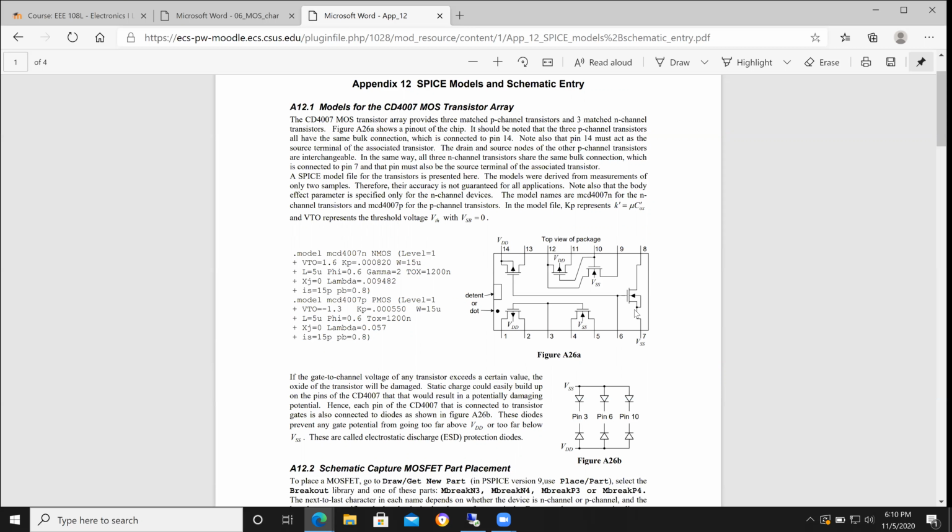You'll understand why later in the lab, but hopefully in lecture you learned about the threshold voltage being 2 components. There's a nominal component, which is bias independent. Then there is a bias dependent component of threshold voltage. And the bias dependent part has to do with the bulk to source voltage. Well, on this device over here, the bulk to source voltage is always 0, because they're tied together, at the same potential.